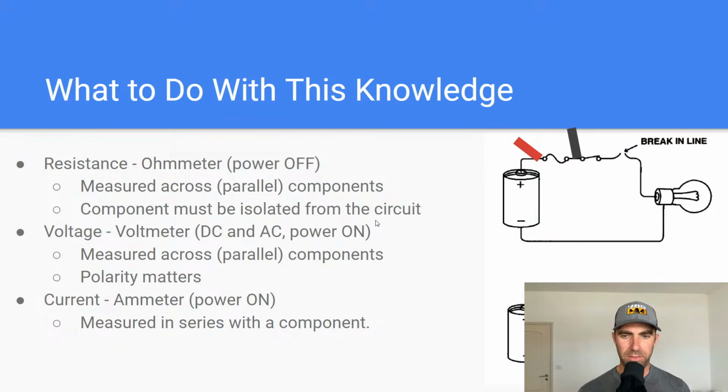And then I think my last note about measuring voltage: one other common thing that you would do is measure the voltage at a connector. So let's say we had an electrical connector that was hooked up to this light bulb over here. We would disconnect the connector and turn on power, and you would set your red lead here, and then connect the other lead to the aircraft ground, like a bare metal part on the airframe.